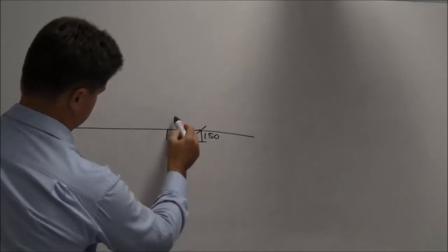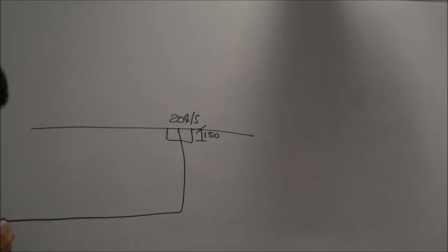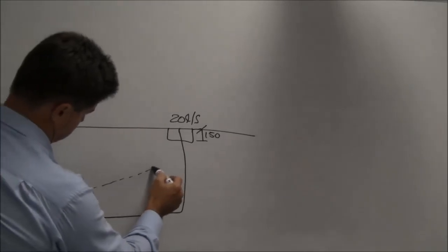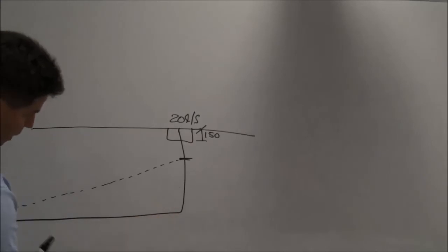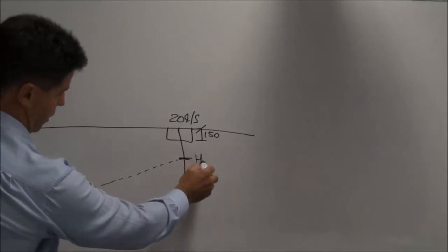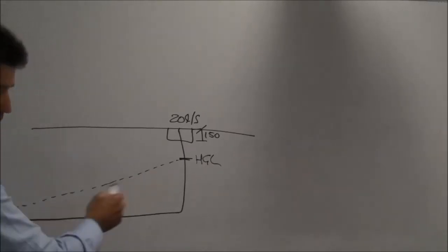Let's say it was 20 litres per second coming into that pipe, and it's just charging out somewhere. If the pipe hasn't got any other manholes associated with it, we normally work from the top of the pipe, and our hydraulic grade line works back to a point. So with that depth of pipe, our hydraulic grade line back here is what we're working on. That's our friction slope.